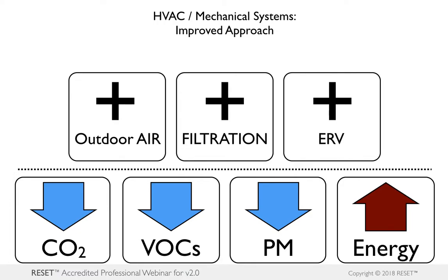So then there's a fairly new innovation that's pretty exciting, which is the energy recovery ventilation, or ERV systems, that are getting more traction today. And we're seeing a lot of them installed in addition to filtration. Now, with this improved approach, we can potentially reduce the energy demand, or at least get it down to some baseline levels, and aim to have filtration medium that can actually deal with the particulate, VOCs, that type of thing.